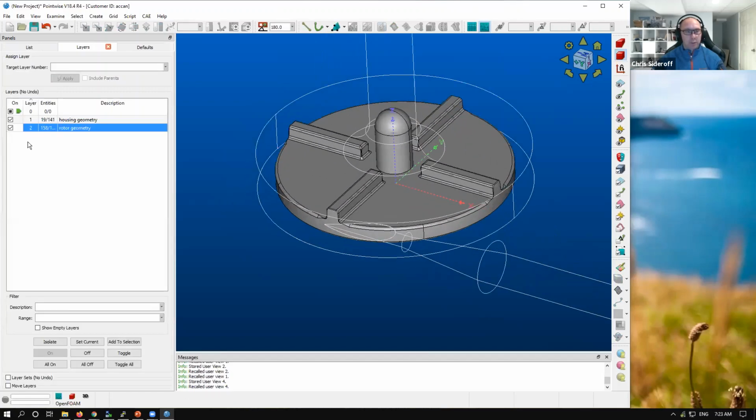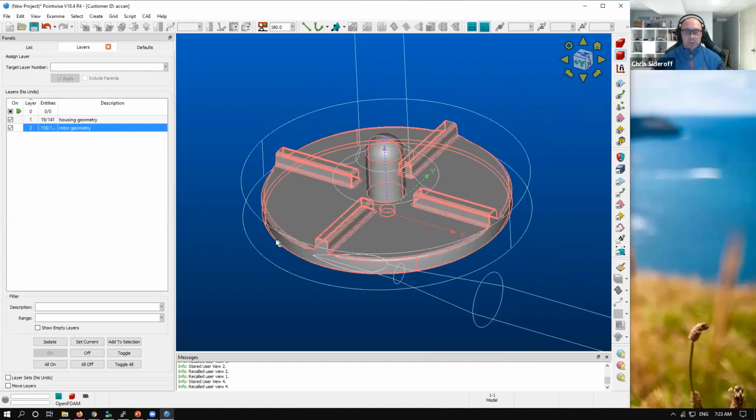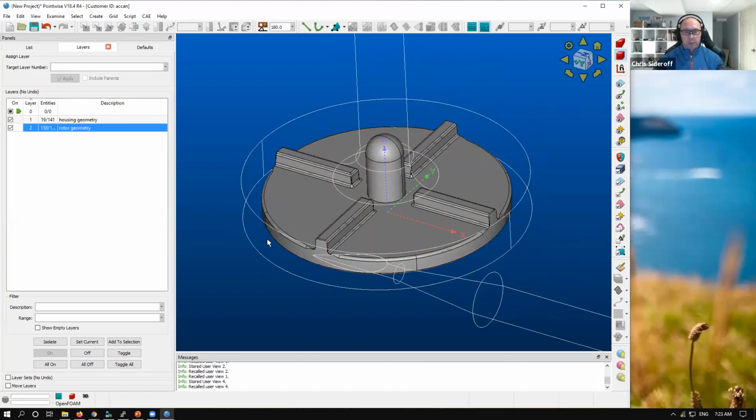The one thing that I'm going to fix here a little bit, though, is how Pointwise works. It's a bottom-up method. We start by creating grid points, which it calls connectors, then we make surface meshes, which it calls domains, and then we finally assemble the volume mesh, where we use blocks. We assemble the blocks from those domains. Now there are some ways to shortcut that. We're going to have Pointwise automatically make us domains and connectors on our geometry.